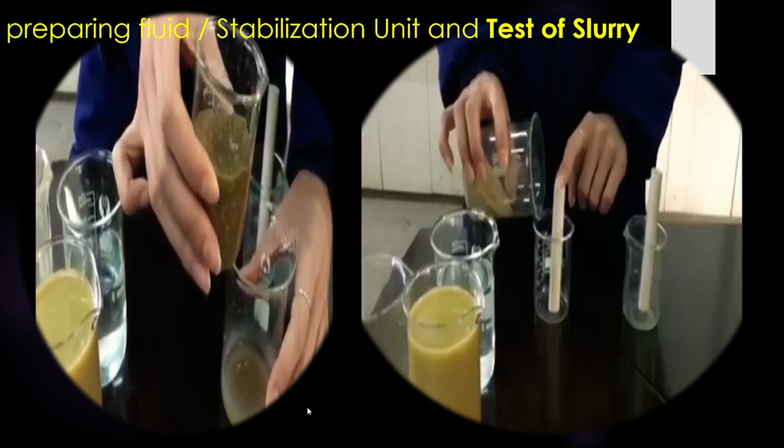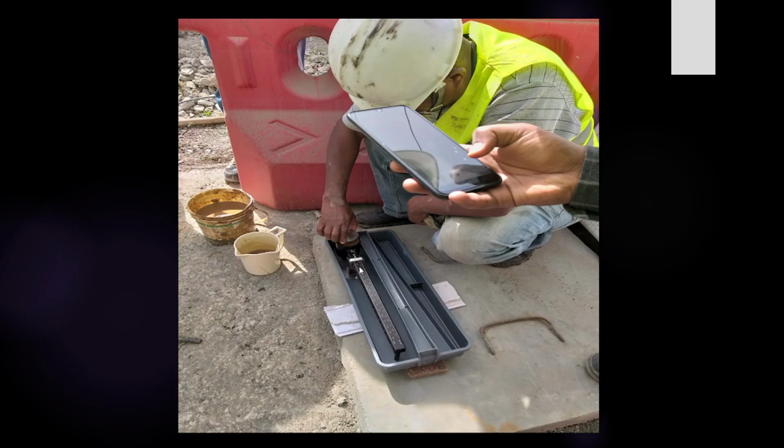So how are we going to test this on site? We use two test types. The first is a density test, so that we have a proper mix ratio. As you see in this figure, we have a slurry material that we put in here to check its density, and if it passes the required quality, then we go on to the next test.